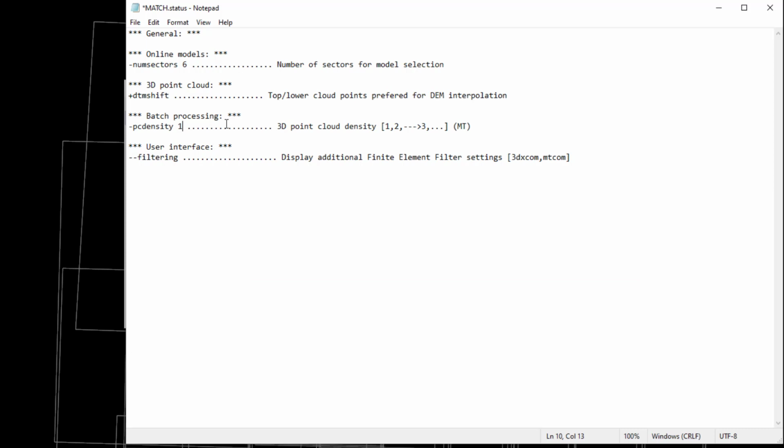quality point cloud. So this is all match status related in combination with the terrain type. Terrain type, perhaps we remember from the PowerPoint, in this case here, has an influence in general about cell size, filtering, and also about gross error detection, and automatically. And now additionally we can manually also add here the filtering options in our user interface. So we activate this one now, and I will showcase immediately where this will show up.